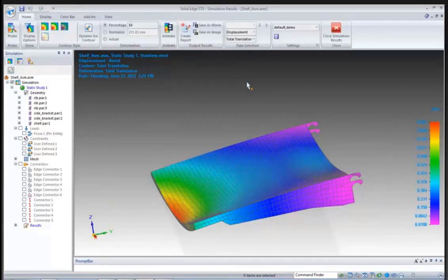It works, and it may work for years, but the problem is you may be spending more money, and your competitors may be coming in and undercutting you because they can make it for less. Here, in this case, we could use a higher gauge sheet metal, which would make a thinner part, which would save us material costs. So you can not only use this for new parts, but also for parts you're already making to see if there's any room for improvement. Because it's so easy to just click that solve. Once you've got a good model here, now I'm satisfied, I can click resolve and try different things moving forward.